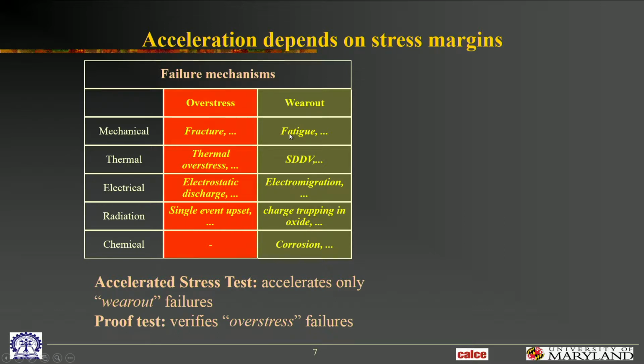And this is a debate that's rampant in the field. People get very nervous the moment you say, I'm going to raise the stress levels and test at an elevated stress in the lab. All the component suppliers and the designers and everyone gets very nervous. Whoa, wait a minute, what do you mean you're going to accelerate the stress level? The product was designed to operate at 85, and the spec says can't go above 85. How far are you going to go? So the idea is that you're going to accelerate it above your use conditions. If your use condition was 35, just to give you an example, and by 35 I mean a temperature of 35 C, relative humidity of 35%, how much can you raise it?